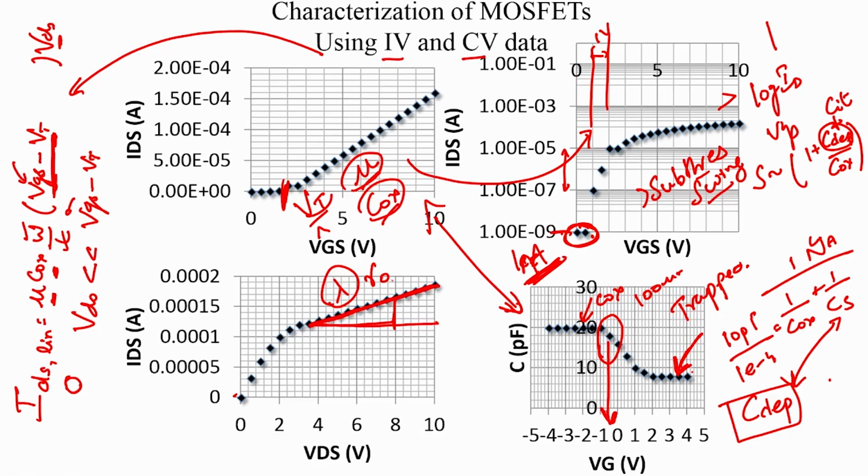So, what do you mean by the output resistance of a MOSFET? It is the output small signal resistance of a MOSFET, which means that if I were to set this as my DC operating point and fluctuate VDS around this point, what is the fluctuation in the current, and that slope or the inverse slope of that tells you the output impedance of the MOSFET.